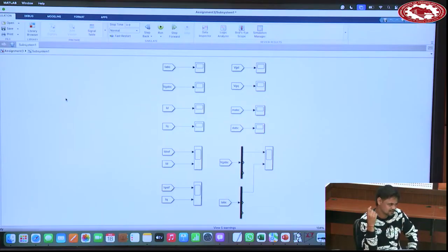We have divided one factor as VDC by 2. Yes, ideally we have to divide VDC by 2. So the DC link should be chosen appropriately so that in the rated condition your converter operates at 0.8 or 0.85. If you have taken the DC link too small, you have not given any margin. You said that at rated condition, 10 kilowatt, the converter is designed for 10 kilowatt power. So when it operates at 10 kilowatt, it will have modulation index 1.